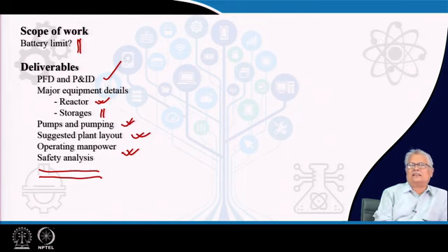I suggest that you attend and get some idea of hazard analysis by HAZOP, particularly for this type of operating plant, and try to do it for yourself first. That is going to give you a fairly complete process design which you can document and send to your client.